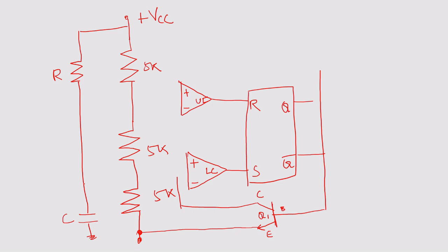and connect it to the capacitor network. In the top, this end should be connected to the collector terminal of your PNP transistor. This is your emitter, this is your collector, this is your base, this is a reset pulse. So this is a VREF.